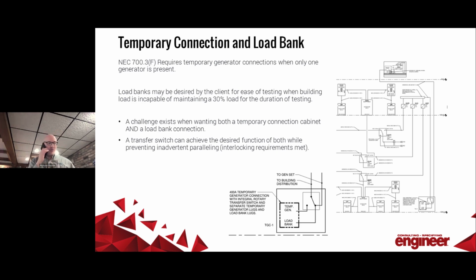Now, we know that we have a requirement for installation, acceptance, and operational testing using load banks. You can do that manually, or you can provide a load bank. And if you're providing a load bank, you might want to look at NEC 700.3(F), which is going to require a second generator connection if you only have one. That's in case you're changing the oil or whatnot.